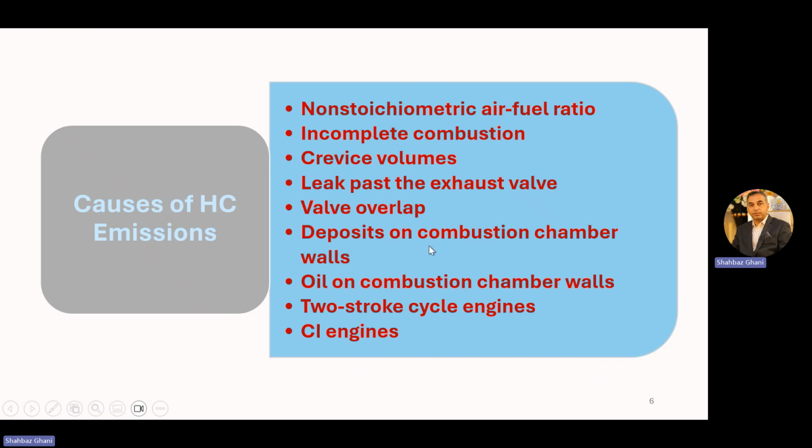Then, deposits on the combustion chamber wall. A few molecules of fuel are deposited on the combustion chamber wall, or there is an oil layer on the combustion chamber wall. The combination of both will also affect the combustion properties in the combustion cycle, so this will also lead to hydrocarbon emissions in the end.